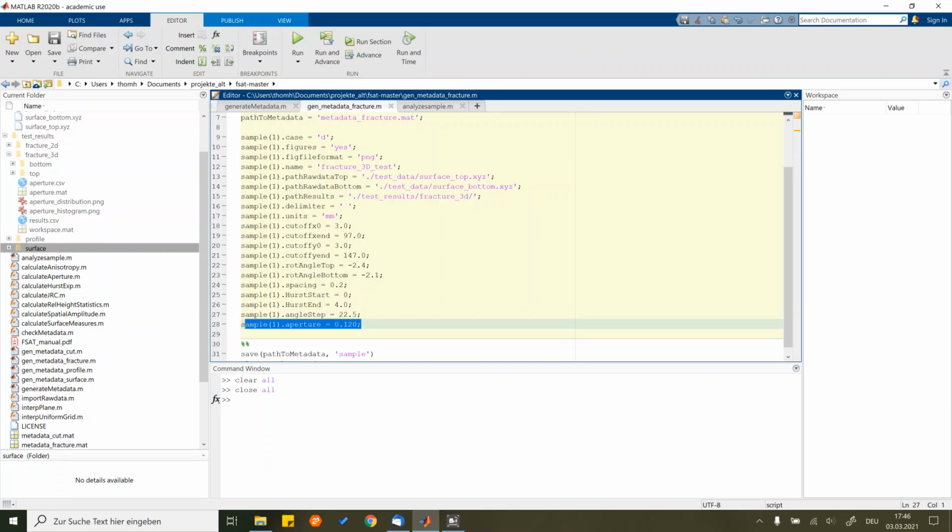And then you can provide, again, similar to the two height profiles, which be a cut through the fracture. You can apply here an aperture. So both fracture surfaces will be lowered to each other until this aperture is achieved as a mean mechanical aperture.